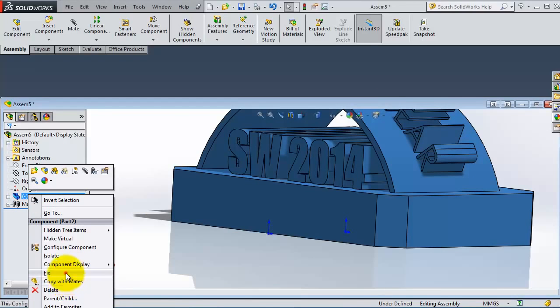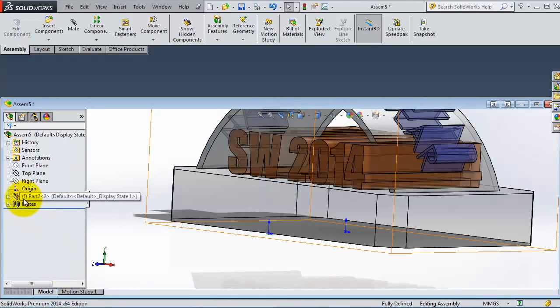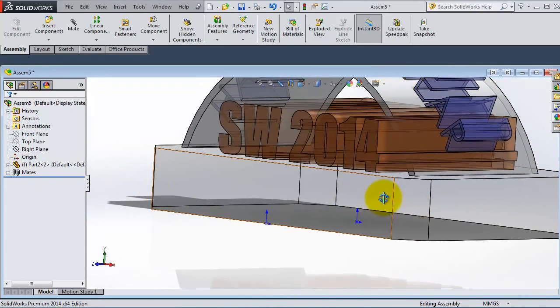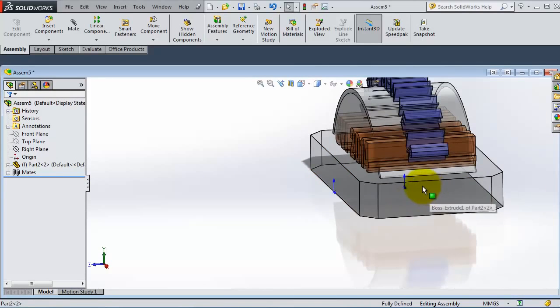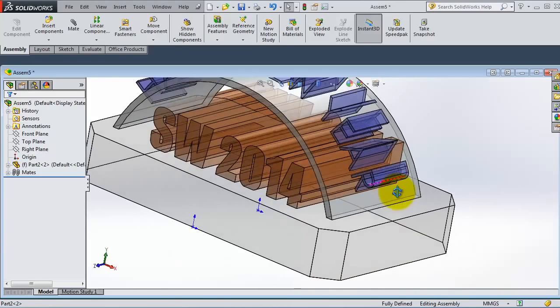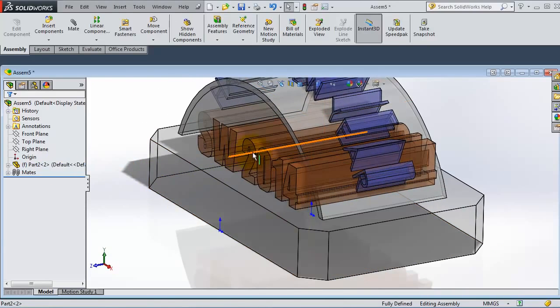your first part, you will see the F sign at the beginning that indicates that your part is fixed. So this is the meaning of the F. That means you will not be able to move it around unless you float that option.